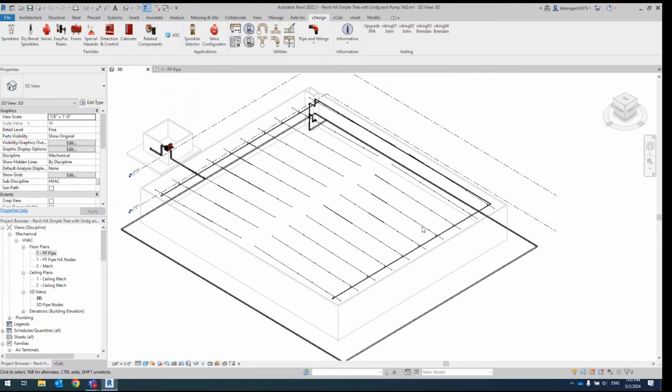So the idea is that you've already got your Revit model laid out when it comes time to run your hydraulic calculations. Obviously you can do that just through vanilla Revit. You could use some of our utilities and our families. But basically all we're really expecting is that you've got a well-connected Revit model. And as you'll see as we go through the process of running calcs on it, we're pretty agnostic about how you actually model the system and what Revit families you use. So if your company is already standardized on your own pipe types, your own fitting families or sprinkler families, etc., that's all perfectly fine. And you can continue using those while using the vCalc program.